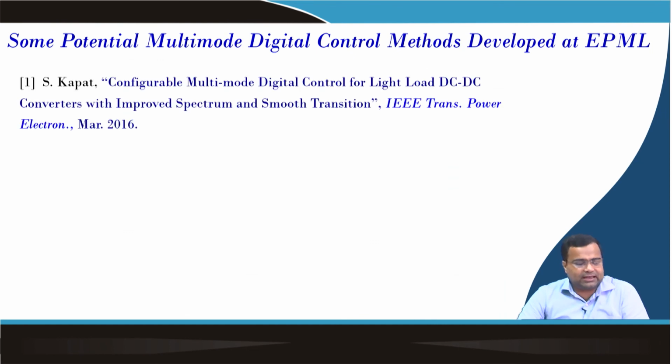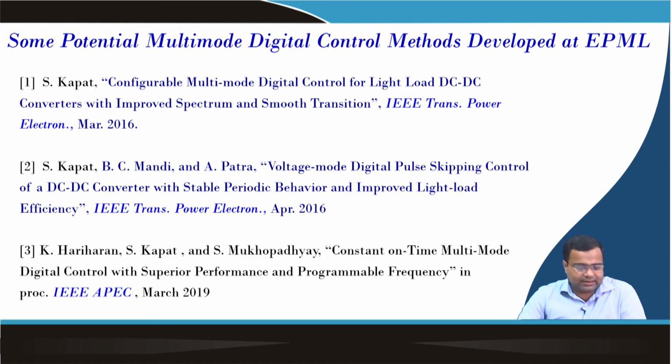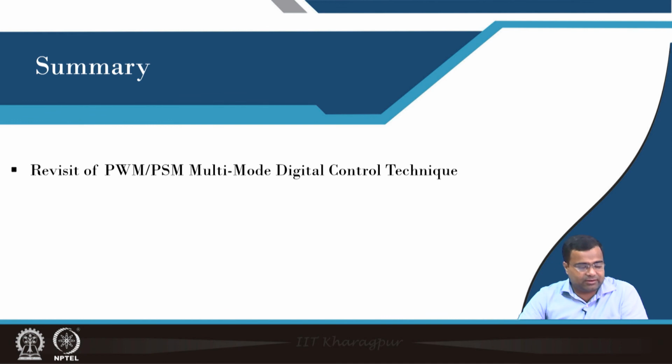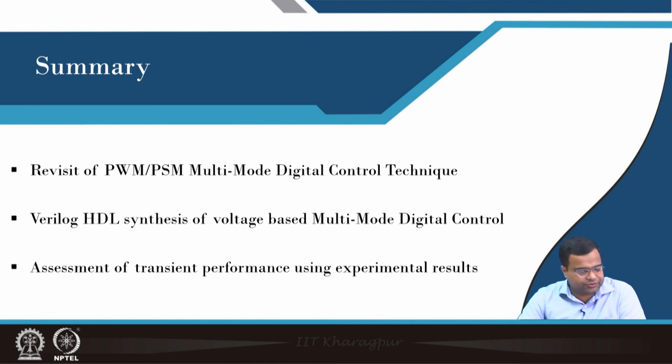And in this we have some work in the context of multimode that can be useful for pulse skipping control basically, and this can also be multimode constant on time, pulse skipping, and a combination of PWM. So, all these things are discussed here. So, in summary, we have revisited our PWM PSM multimode digital control, Verilog HDL synthesis of voltage based multimode digital control. We have also made some assessment of transient performance using experimental results.